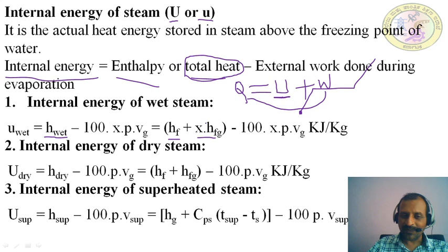Right? So then what is the use of this steam table? Whenever you need to solve the problem, you directly take down the values from the steam table. HF value directly you can pick here, this value. HG pick from here directly. So instead of calculating using those formulas and wasting time here, you can further proceed by taking the values from this steam table. So that is the use of this steam table, right?